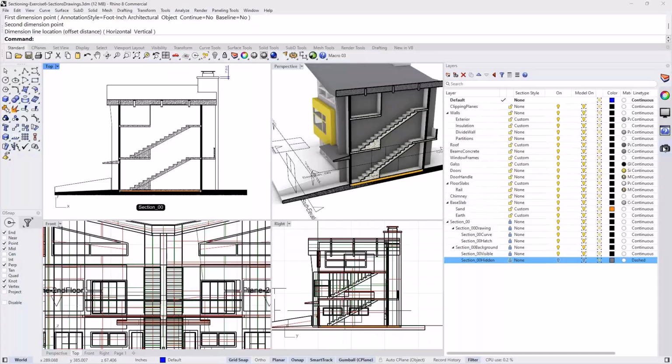Just try it now and see if that works for you. The drawing should update, especially if your section is set up to section through all objects, because you can set up your section to section through just layer X, and if you add a million objects to layer Y, nothing is going to happen to the drawing. So yeah, if you see it clipped by your clipping plane, it should also update with your drawing using the update the clipping drawing command.